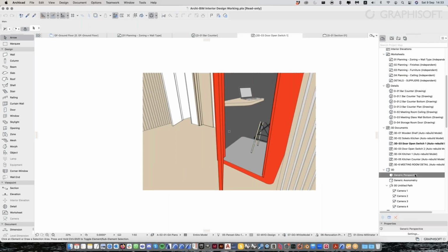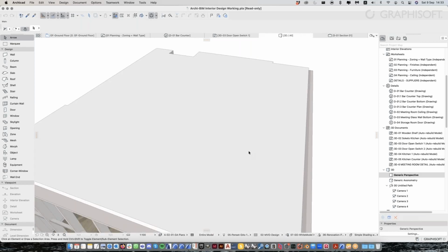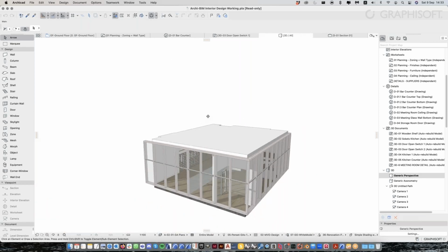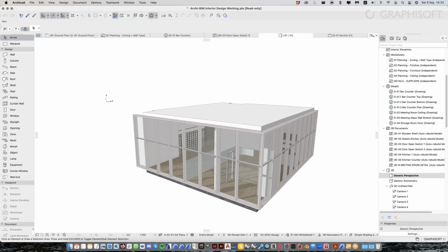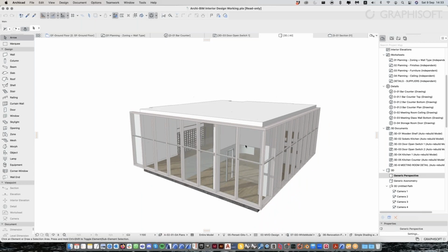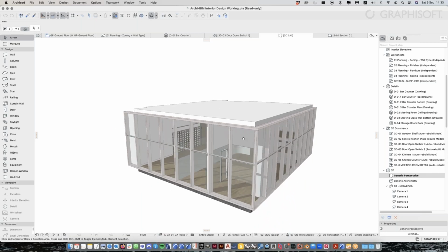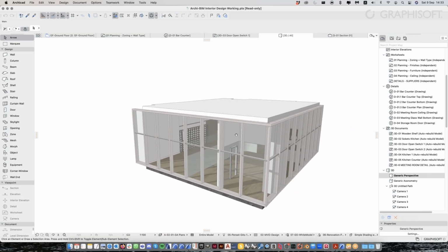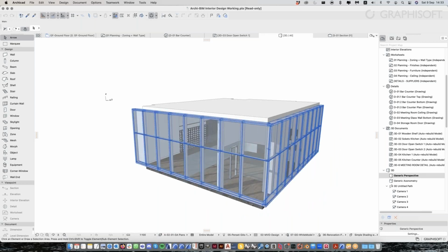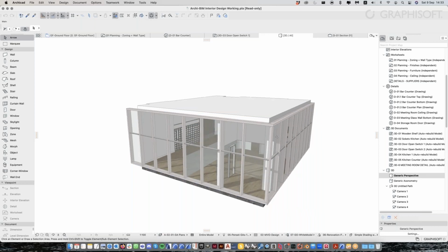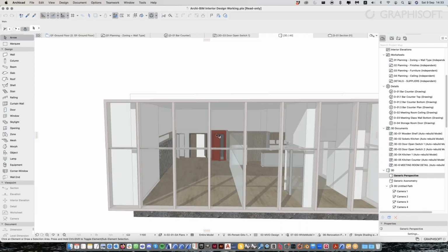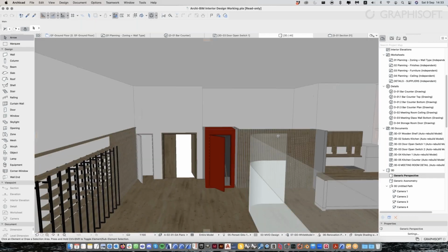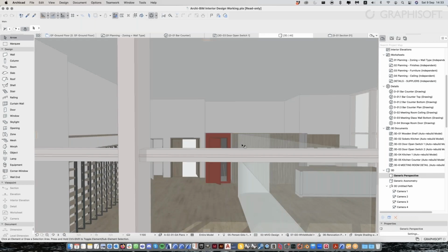And of course, you can look at your model in a 3D view, so the perspective view. If you want to, in the 3D view, you can zoom in using your scroll wheel. You can pan by clicking and holding on the scroll wheel. And if you want to rotate, you can hold Shift and also hold your middle wheel, and you'll be able to rotate. So we'll be doing this a lot in today's class, just checking out the model that you have built, okay?